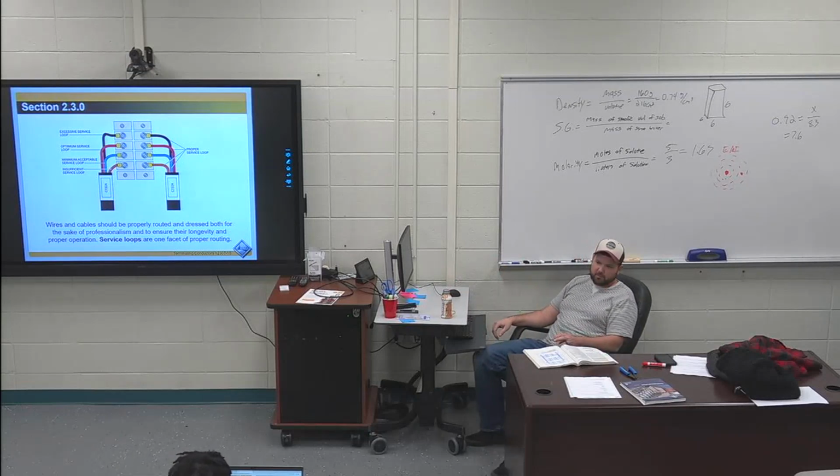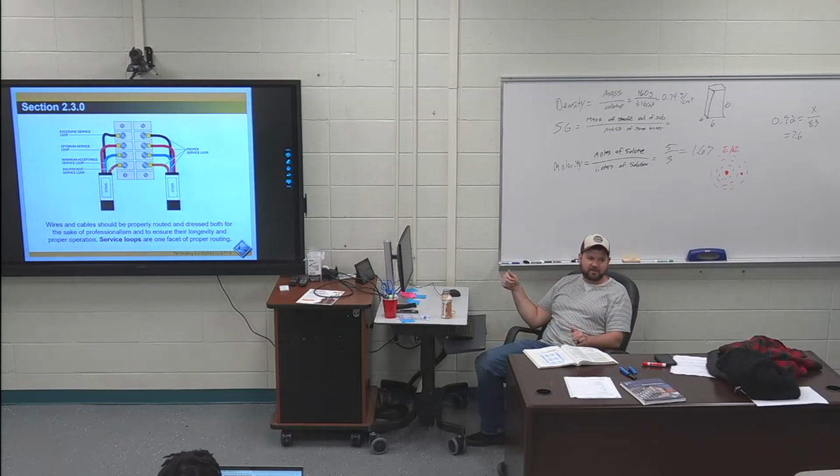Do not put 6 feet of wire inside of a box for somebody in case you need it. I see too many people do that. They do a big long pull and stuff like that, and it's not easy. And they'll wrap up 6 feet of wire and shove it inside of a box. That causes more issues than not. You're never going to have to trim back however many feet of wire.